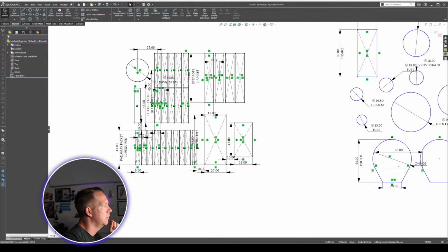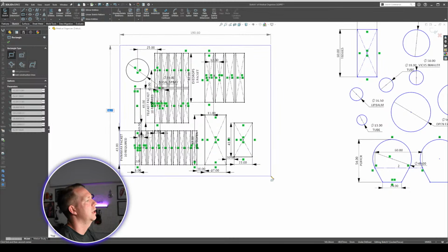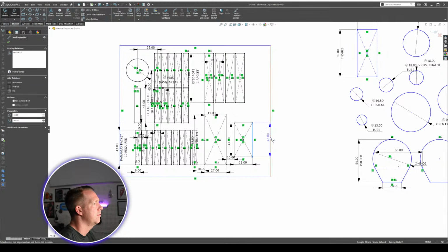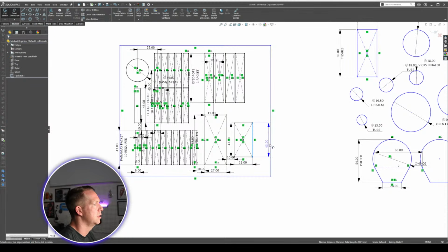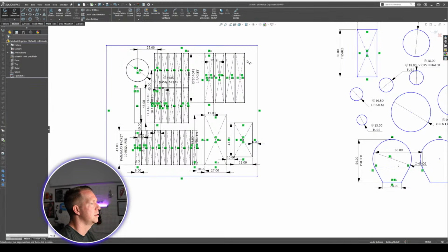I'm just going to add a frame around this now. I'm going to have the minimum wall, which is, okay, from anything that's in here, I want a minimum sort of space between it. Between this and this, so let's say 6 millimeters.